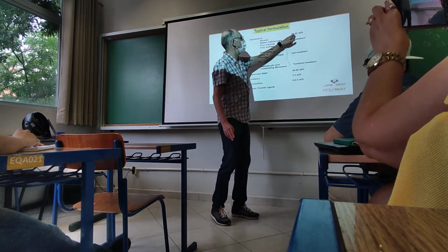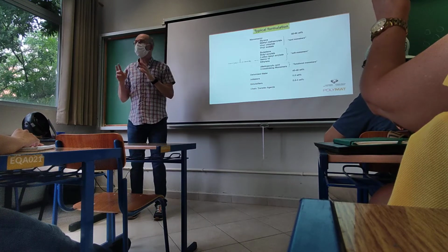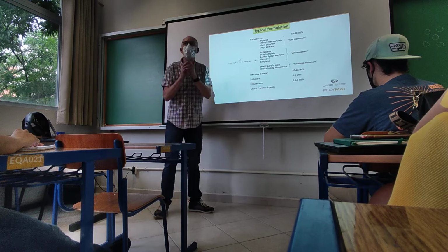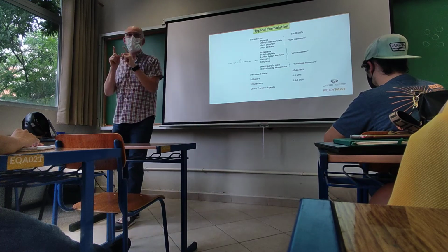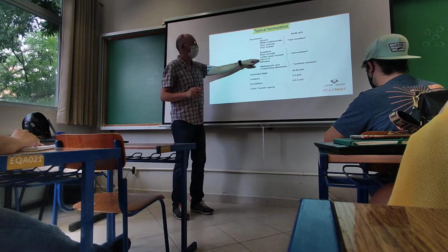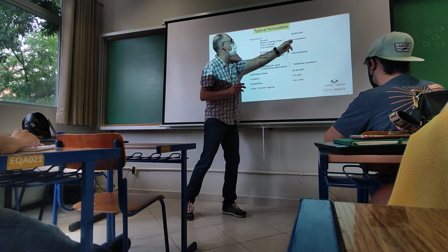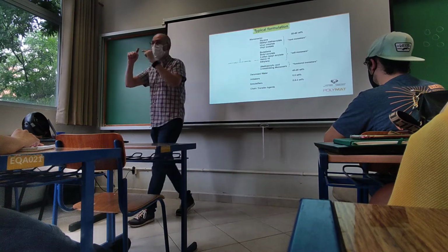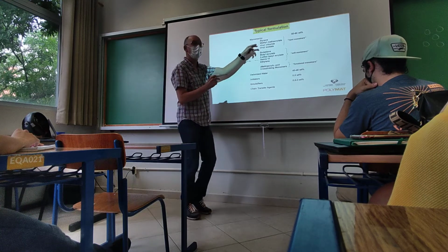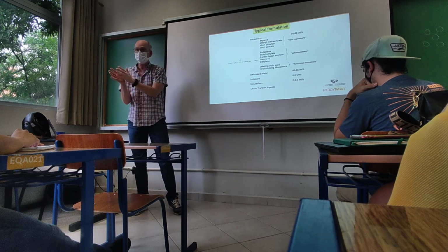Monomers, which are between 50 and 60%, and in any commercial formulation, you will have 2 or 3 monomers at least. Okay? One monomer will be hard. A second monomer will be soft. When I say hard and soft, I mean that their polymers have high Tg or low Tg, so you will combine hard and soft monomers to control the Tg of the polymer that you want.